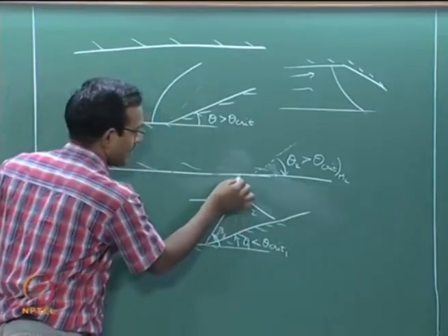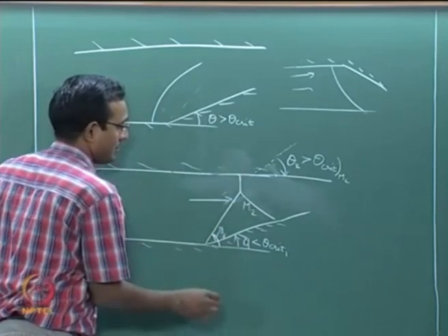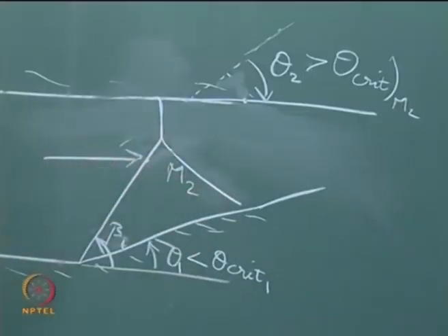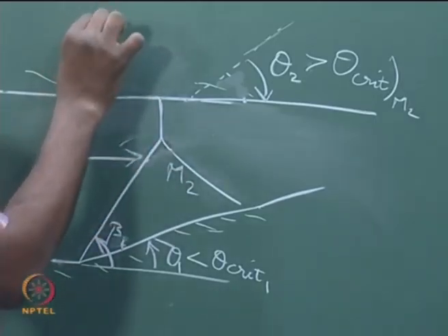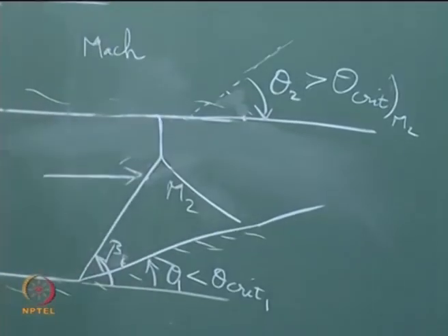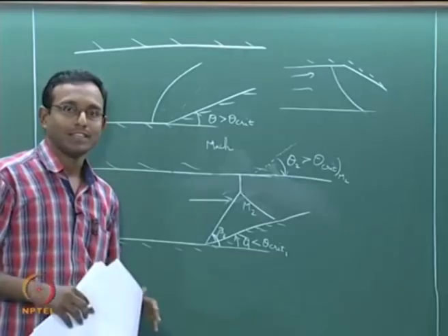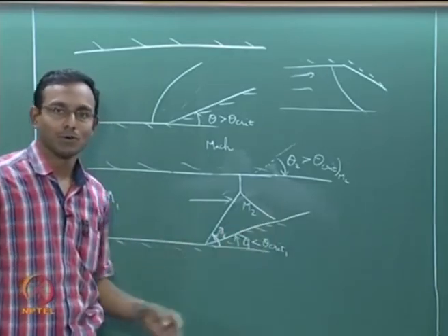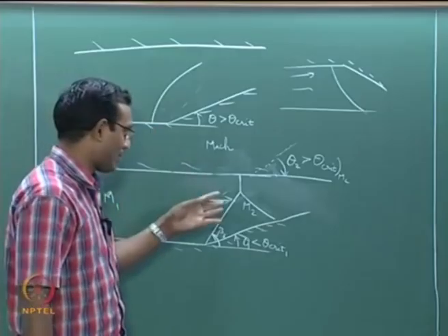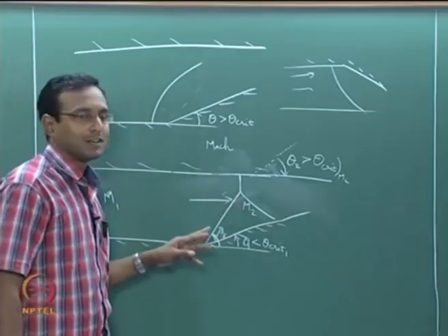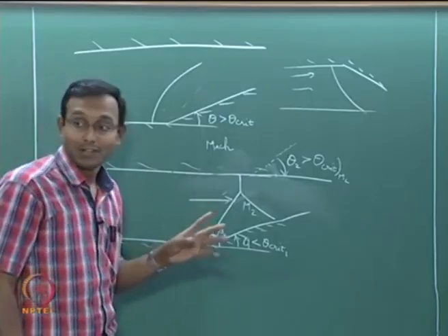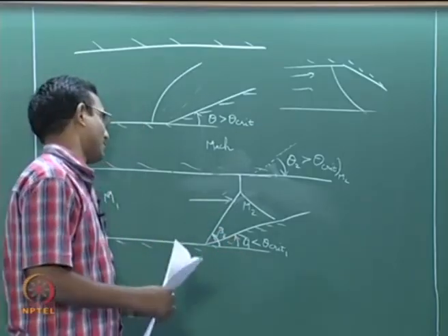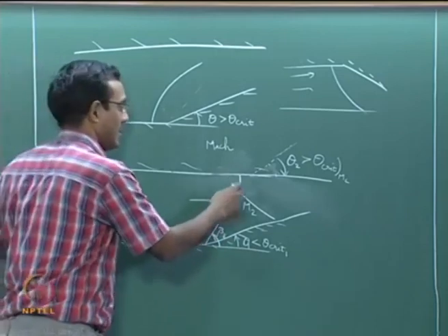What is happening here is there is roughly a normal shock sitting here, and then there is a somewhat curved shock sitting here. This is what is called a Mach reflection. Again, Ernest Mach was the one who explained this very well. He explained it for blast waves traveling across a wall, but anyways it works very well for our case also. This is shock reflection at a wall, explained like this. It could be any of those reflections, all the reflections were explained first by Ernest Mach. Anyways, I am going to have this case.